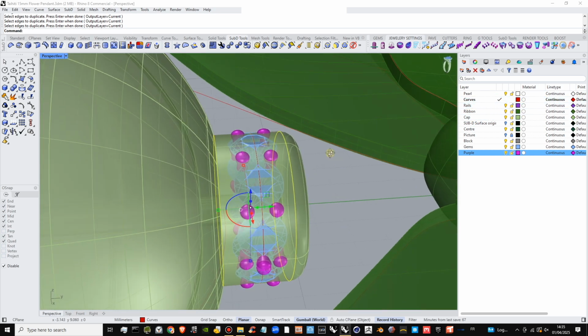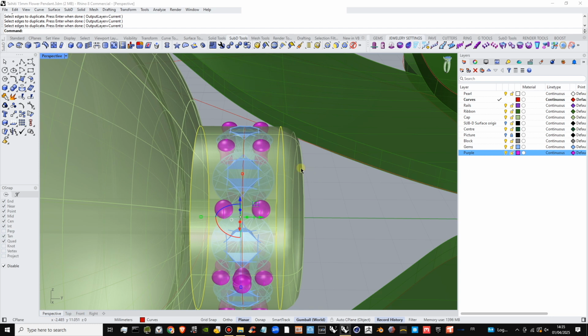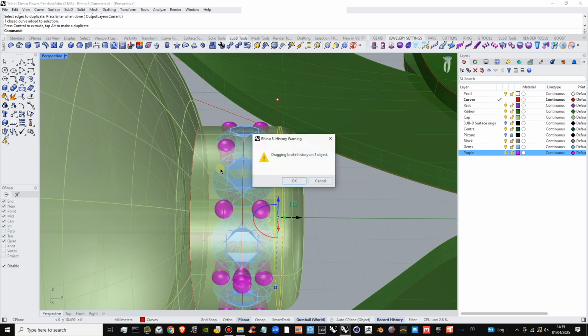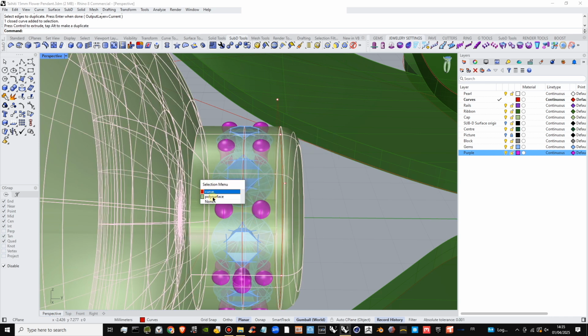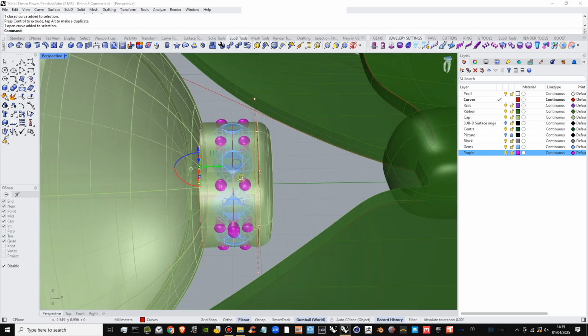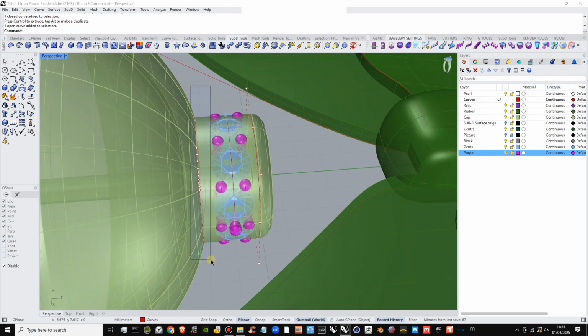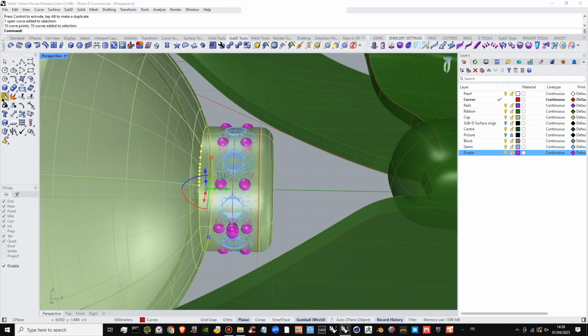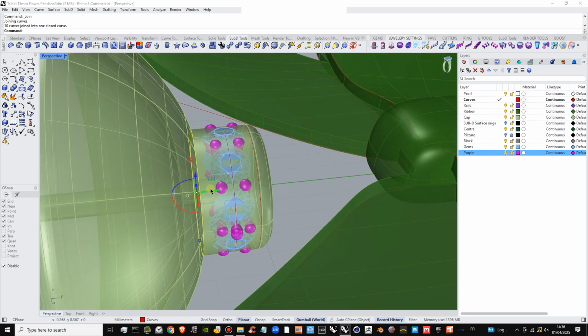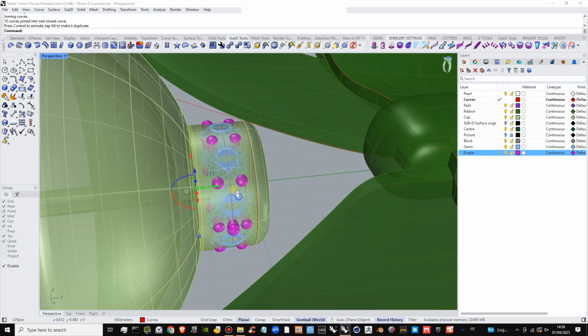And we're going to use those edges to create our bright cut. So I'm going to bring that over a touch. And the same with this curve. And this curve, because it was created from multiple edges, didn't join. So we're just going to have to join that curve quickly. And bring that curve over here.